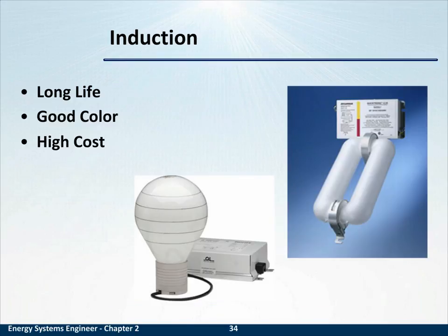This next illumination source, induction lighting, has benefits of long life, good color, but high cost. Induction lighting can last 100,000 hours and have great color. So one rule of thumb is, if the lamp or the fixture is hard to get to, put in induction, because you won't have to replace it for a long, long time.